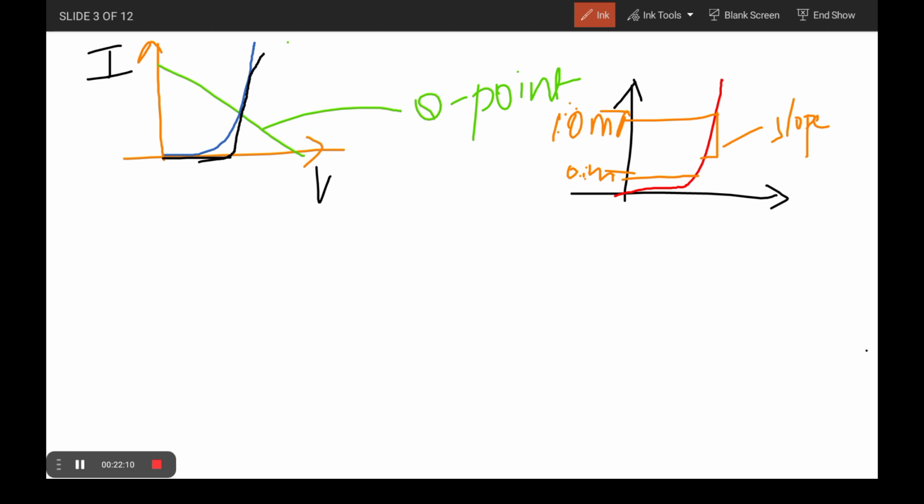So from this point of view, if you want to represent the diode in the equivalent point of view, this is the final one: the diode with some cut-in voltage V gamma, and some resistance. This is the equivalent circuit for the p-n junction diode. The diode voltage is 0.7 volt, plus or minus, with some resistance R.